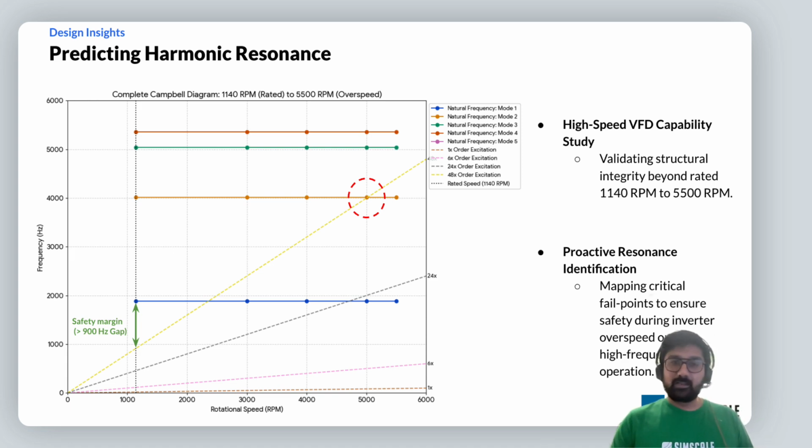That covers our session on electric motor vibration analysis, where we saw how we can set up such a simulation in SimScale, collect the results, and form a Campbell diagram to find out the operating range for the rated RPM, and also test extended modes with different RPMs for the motor.